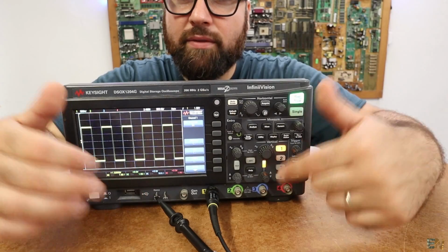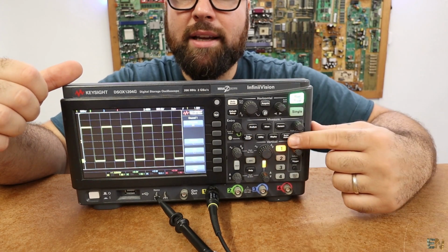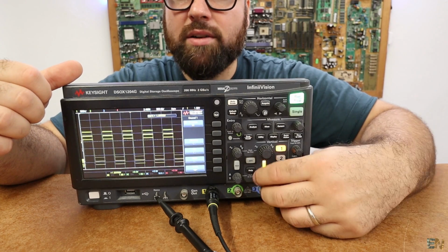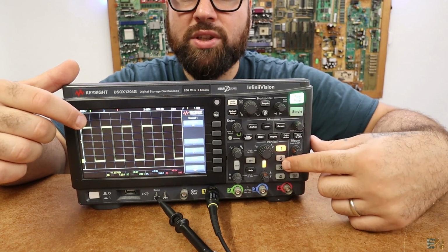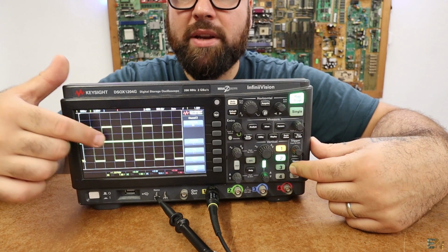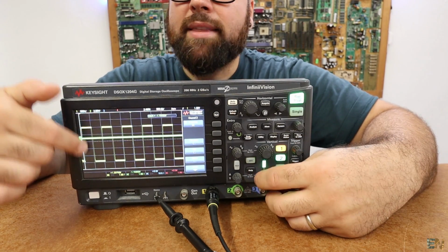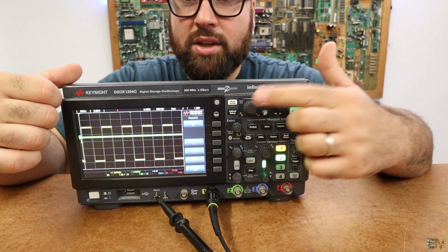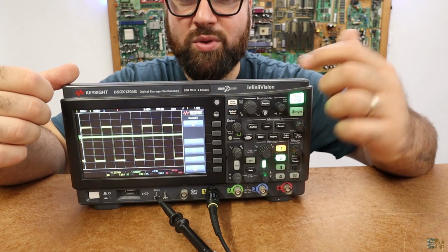We can change the time scale for all the channels, but these two are for each specific channel. As you can see right now, I selected the yellow line. So as you can see, if I move my cursor, I'm moving the yellow line. But then if I select this one, which is channel 2, the green line will appear, and now if I use that knob, I can control the position of the second channel, and I can do that for the third channel and the fourth channel. So these are for all the channels, and this is for each specific channel. That's what we use those knobs for.